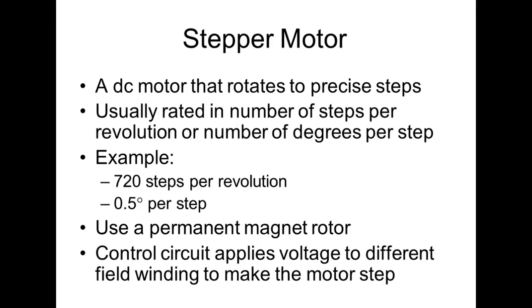The 3D printer that Thomas built is what's called a plastic string printer. So it uses a string very similar to weed eater line. Then it comes down and it does layering too. It's got a print head that actually melts the material and lays it out in a certain precise thickness. And then it builds things in layers too. The problem with string printers is they're a lot cheaper, but it's really, really hard to get smooth because of the string. I can show you.